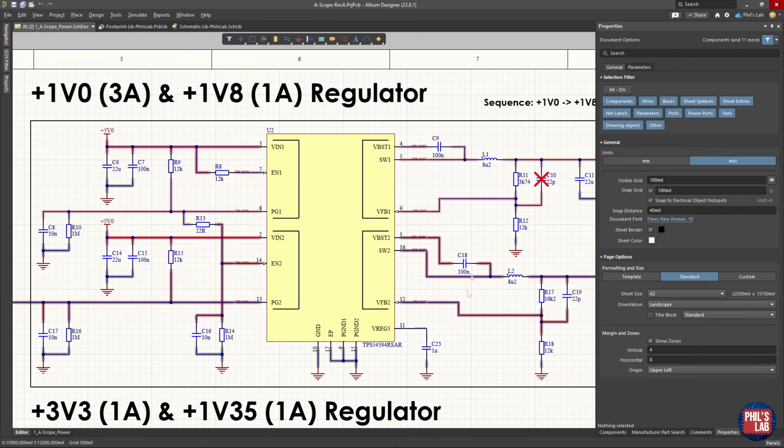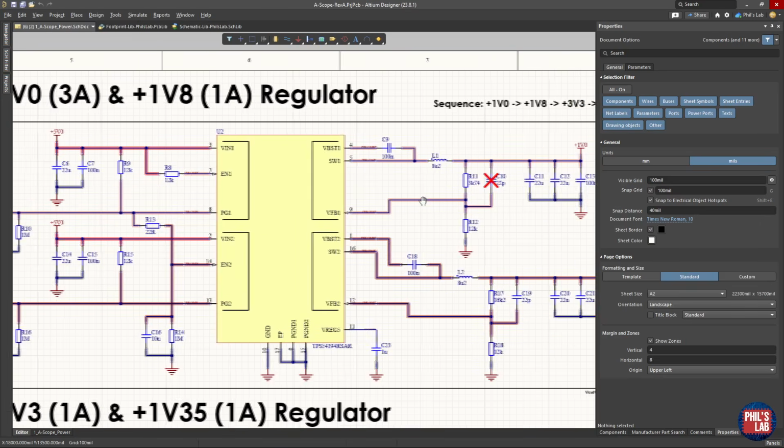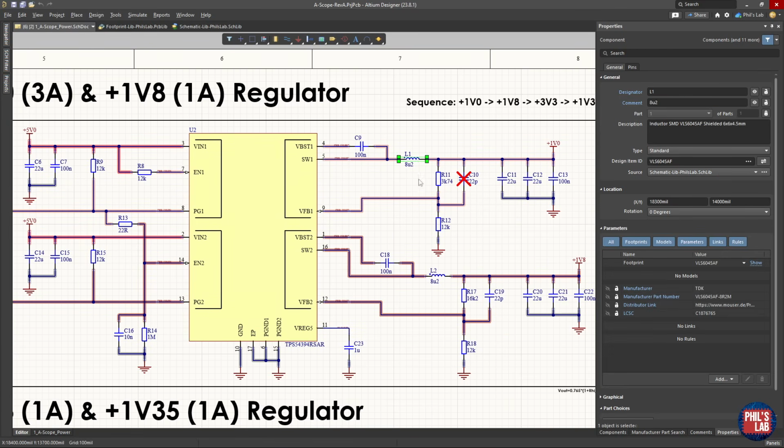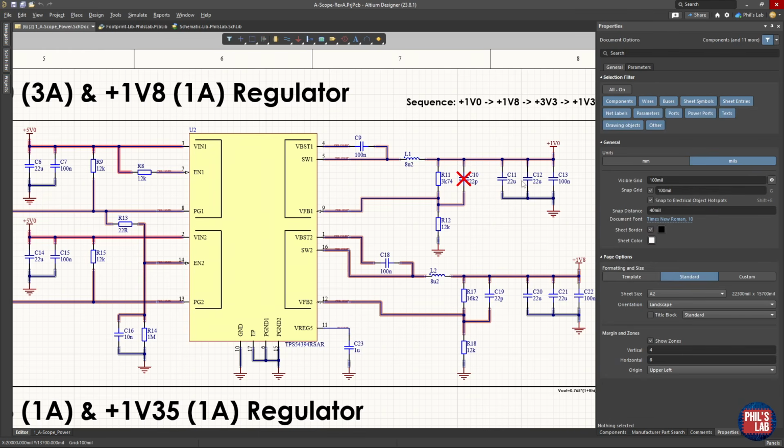For components such as switching regulators, you might have to do a bit more work. For example, this switching regulator here has standard structures around it, such as bootstrap capacitors, output inductors, feedback networks, input-output capacitors, and so on. But these values have to be sized depending on the application. So I didn't pull these values just straight from the datasheet application schematic or out of thin air. You can either follow calculations from experience or from the datasheet.